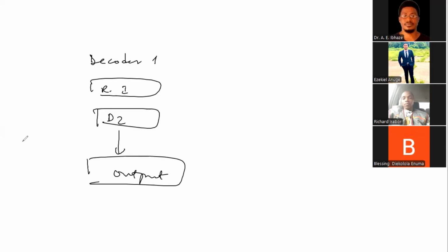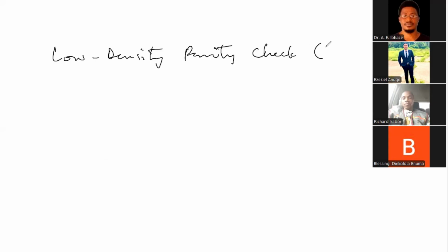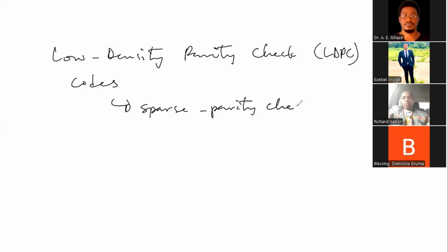Like I mentioned earlier, the block codes and the convolutional codes form the foundation for what we do. Then we have the low density parity check (LDPC) codes. Okay. And this follows directly from the linear block codes. But what happens here is that they use a sparse parity check matrix, okay? So that's H. And this is the same parity check matrix we use for syndrome decoding, okay?